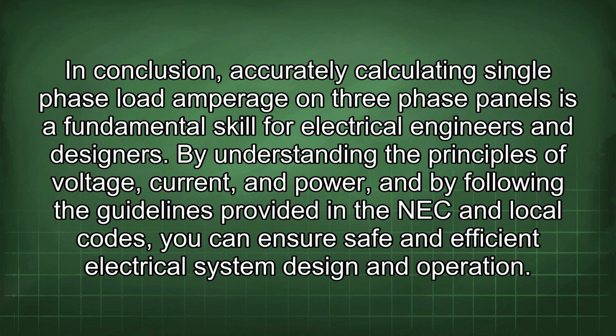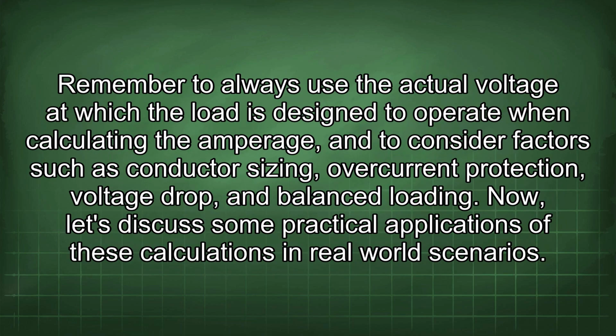In conclusion, accurately calculating single-phase load amperage on three-phase panels is a fundamental skill for electrical engineers and designers. By understanding the principles of voltage, current, and power, and by following the guidelines provided in the NEC and local codes, you can ensure safe and efficient electrical system design and operation. Remember to always use the actual voltage at which the load is designed to operate when calculating the amperage, and consider factors such as conductor sizing, overcurrent protection, voltage drop, and balanced loading.